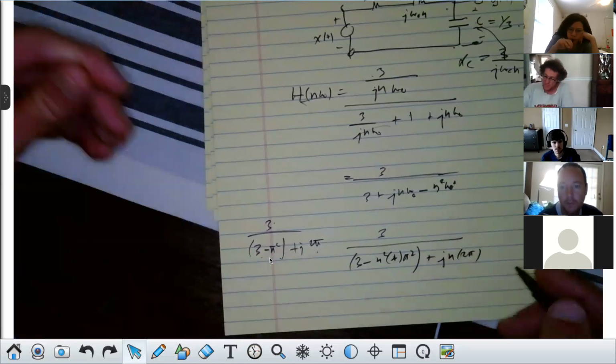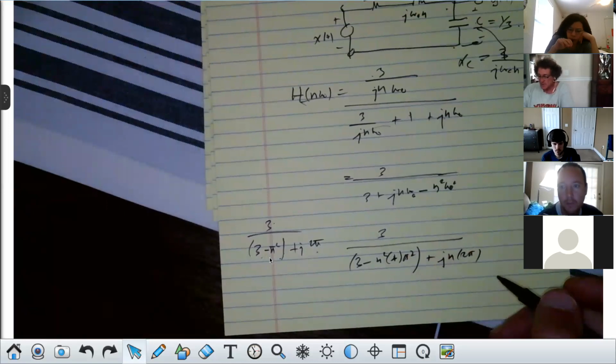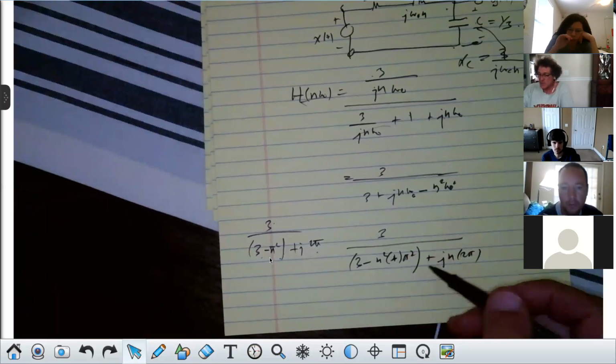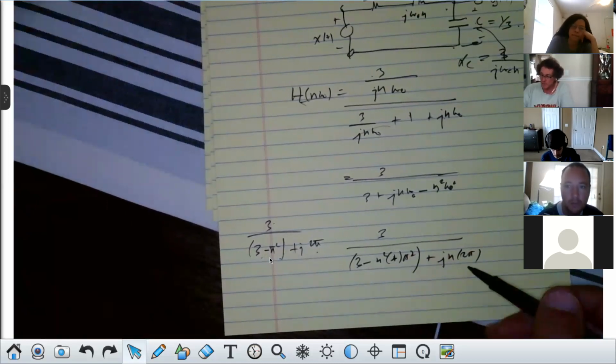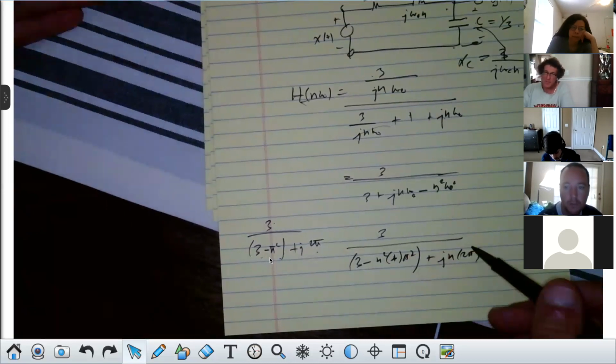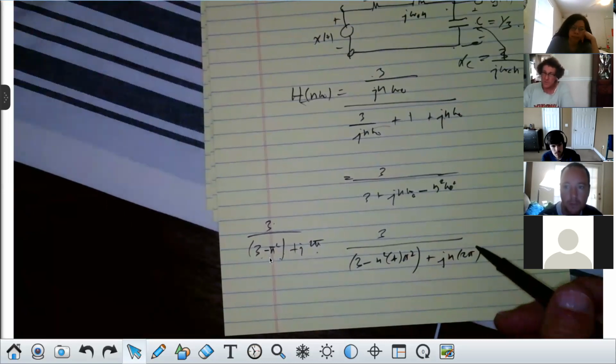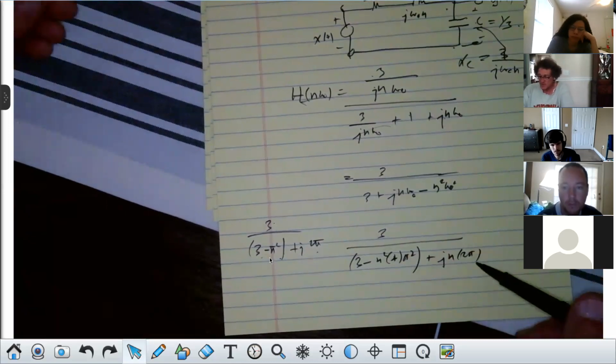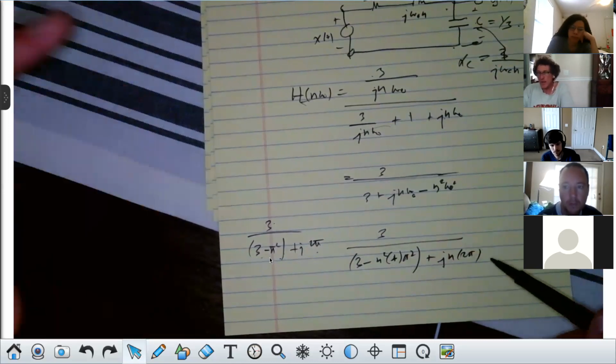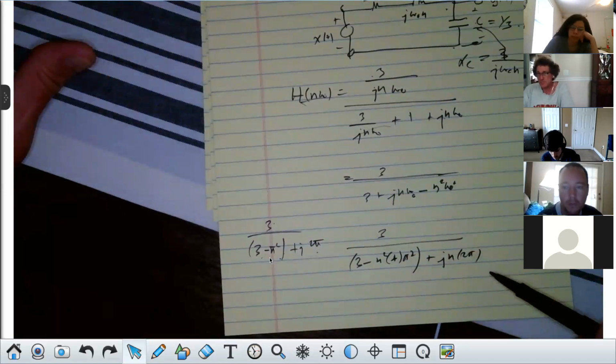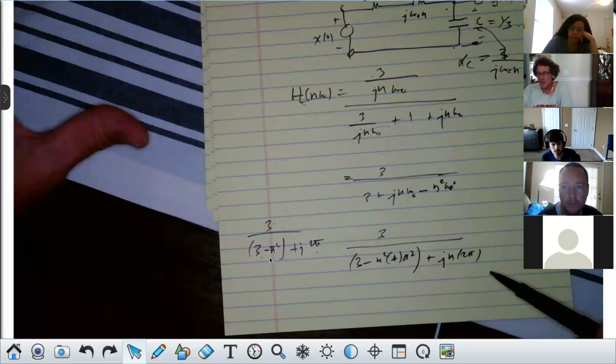This is the filter response. Now, frankly, if you look at this, this does not go to 0 at any point. This thing has some finite value for all frequencies. Do you agree? I mean, as it goes to infinity, it goes to 0. But really, this is a type of low-pass filter. It actually has 40 dB of roll-off instead of 20.